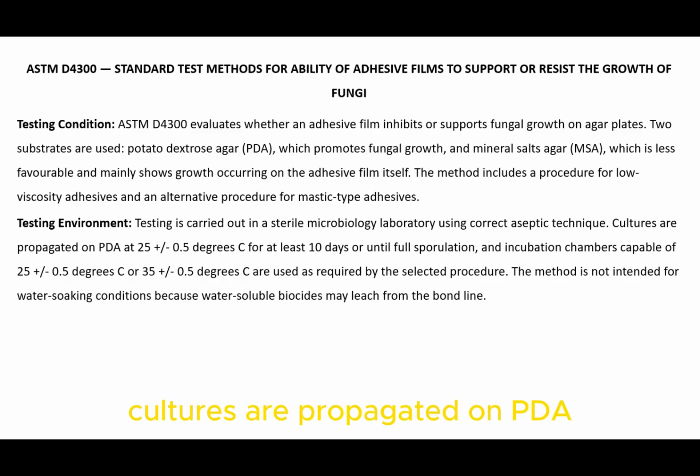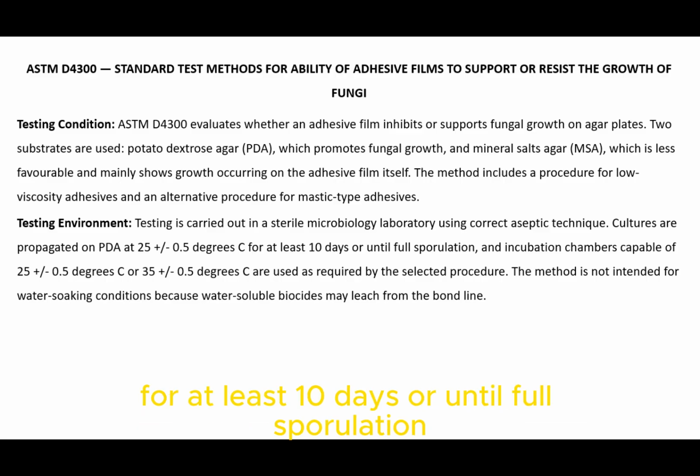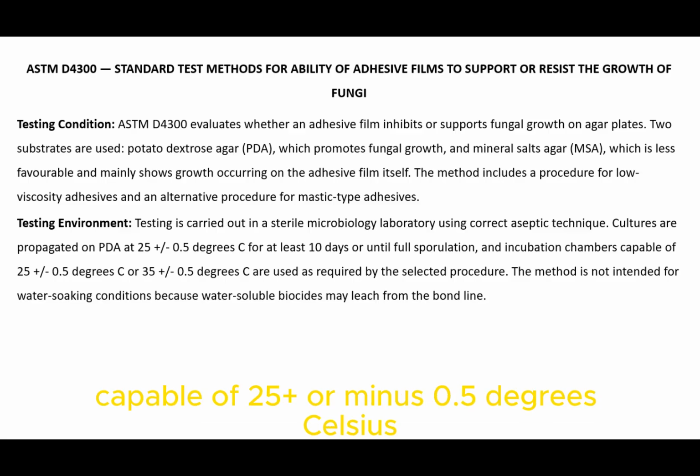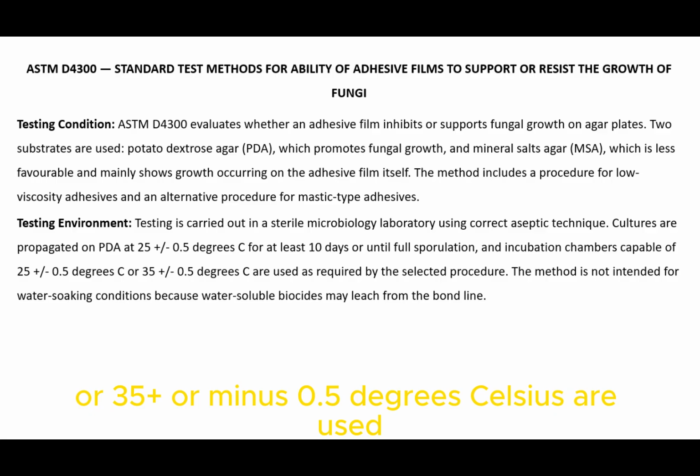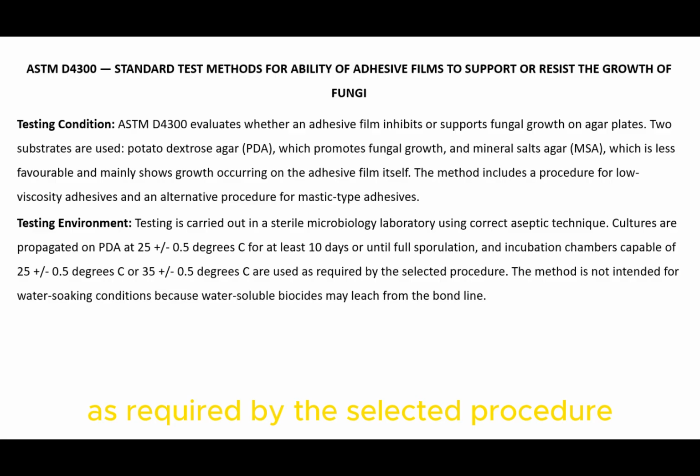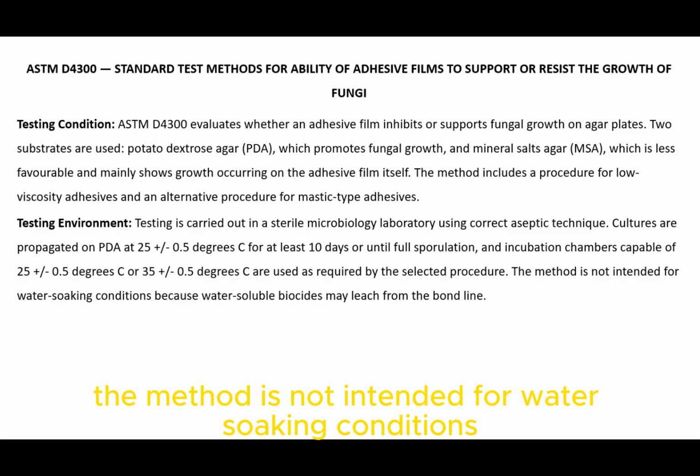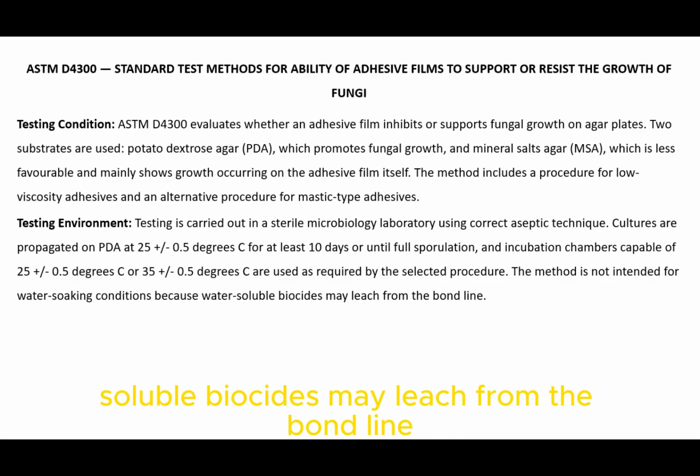Cultures are propagated on PDA at 25 plus or minus 0.5 degrees Celsius for at least 10 days or until full sporulation, and incubation chambers capable of 25 plus or minus 0.5 degrees Celsius or 35 plus or minus 0.5 degrees Celsius are used as required by the selected procedure. The method is not intended for water-soaking conditions because water-soluble biocides may leach from the bond line.